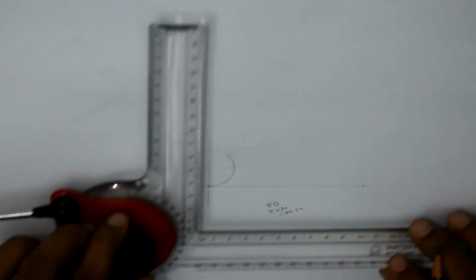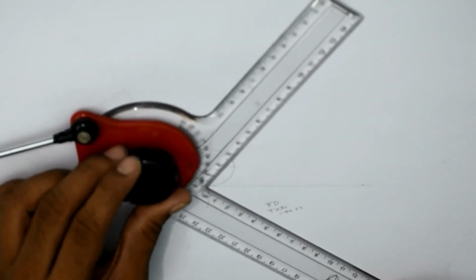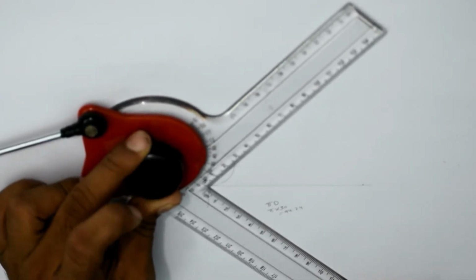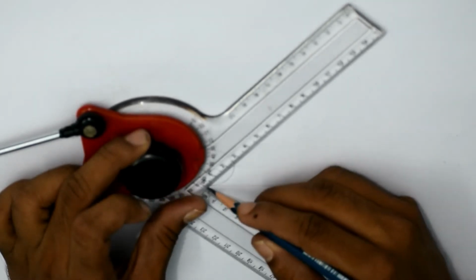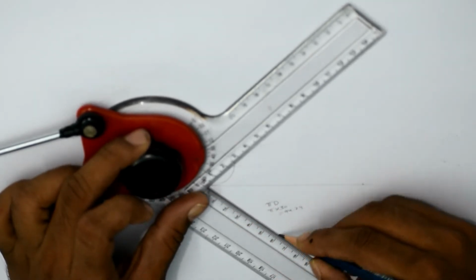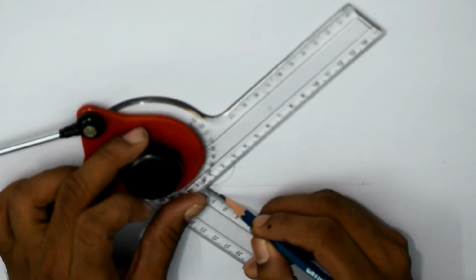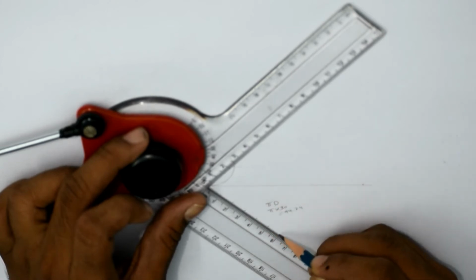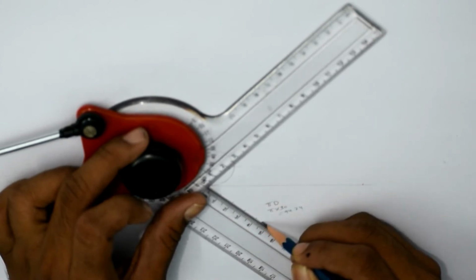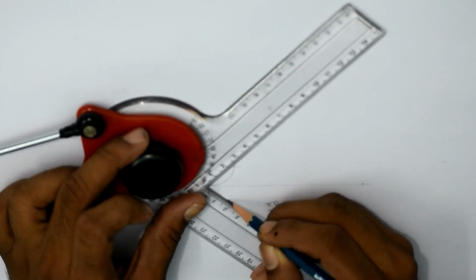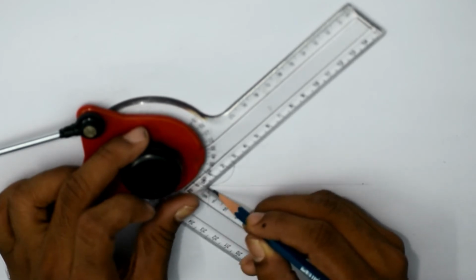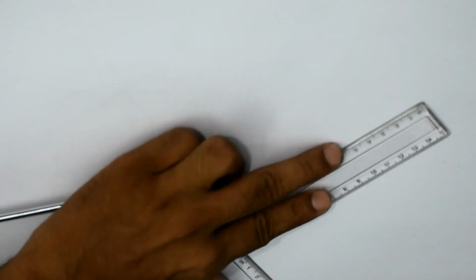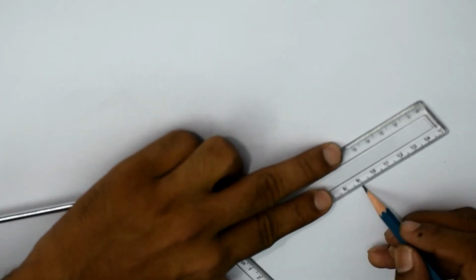And now I am dividing this line into say 12 equal parts, and I will divide the circle also into 12 equal parts. This is the procedure for drawing the cycloid. So observe that I am marking at each 10 mm on scale and also 5 mm divisions. So I have taken 5 mm divisions. So these are 12 parts. When I join this line,